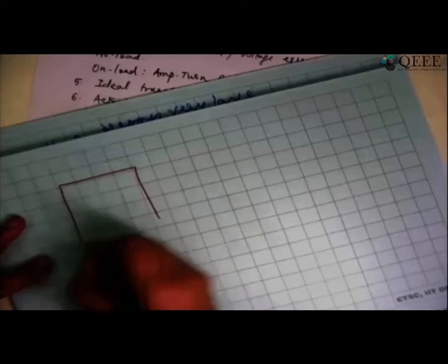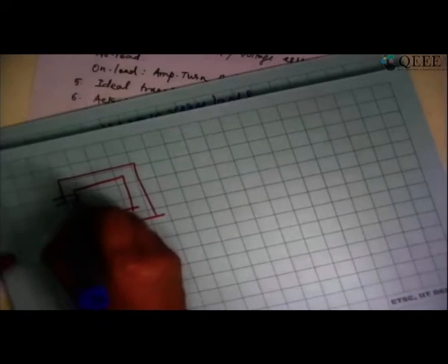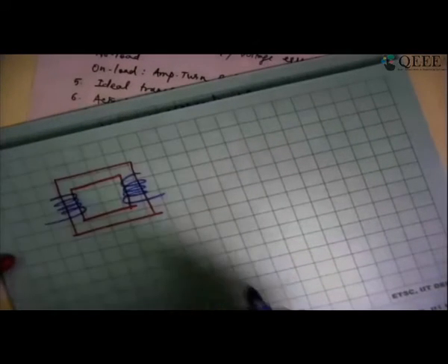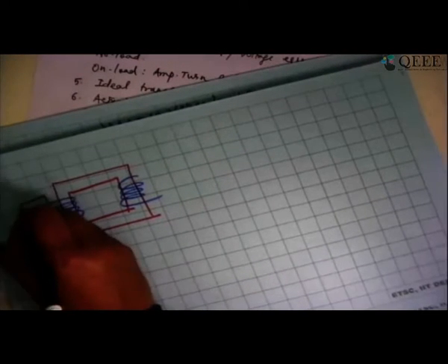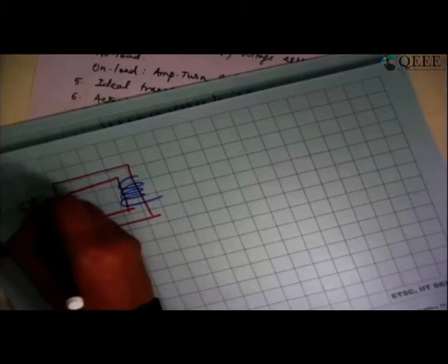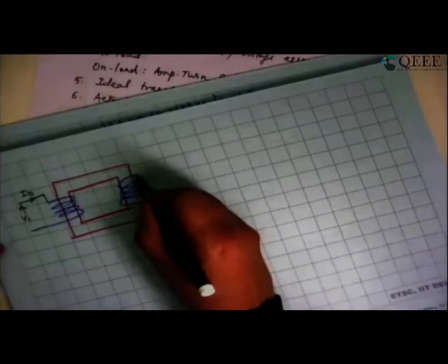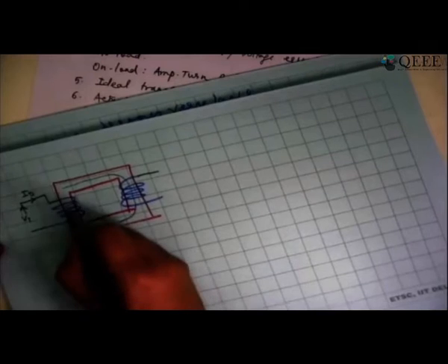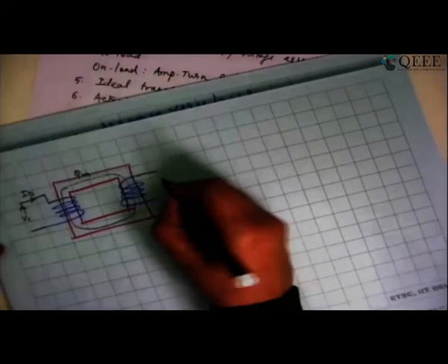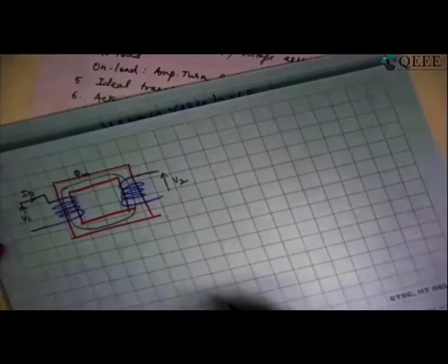Okay. So just to summarize the transformer action so far, I have a ferromagnetic core on which I am going to have two windings wound, one primary, one secondary. The primary winding is excited with an alternating voltage V1, and it is drawing a current of I0 when the secondary is on open circuit. A flux is established in the core, which is known as phi m, and it induces a voltage called V2. When I connect the